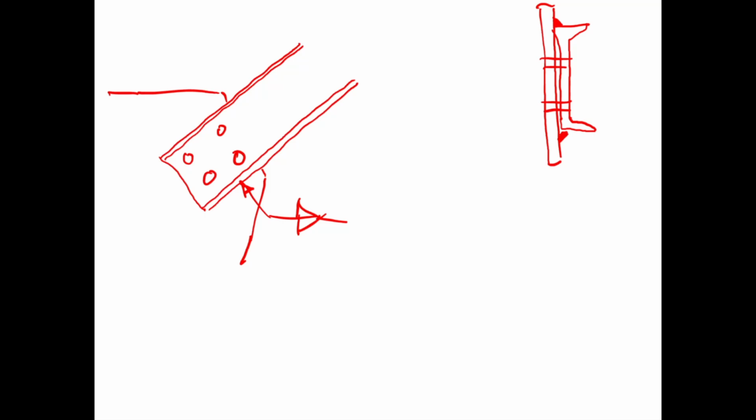Yeah? Why did you choose the channel? I'm showing an example channel. And so it's not uncommon to use channels as a tension-only brace kind of section. We'll see satisfying slenderness with channels is quite difficult because they tend to be quite floppy. So we might have to specify some kind of welded connection like they did for the flat bar in that school I showed you. I'm just picking it to demonstrate how you might design a channel if you were to pick a similar brace in this situation.